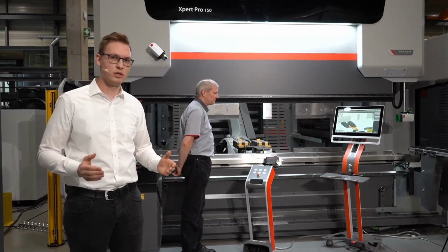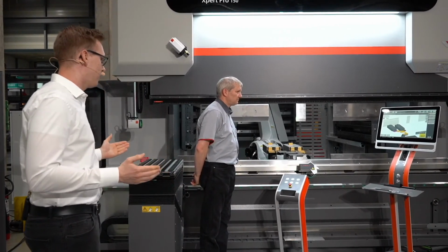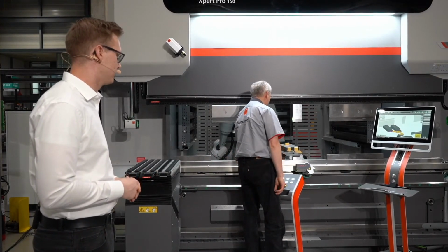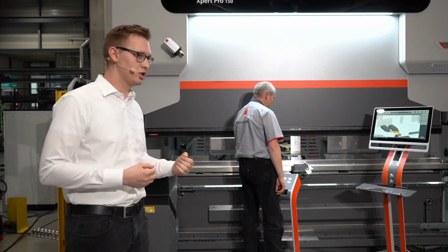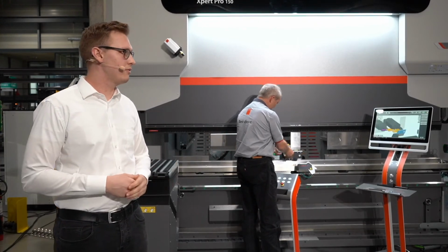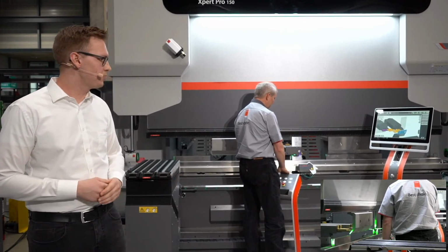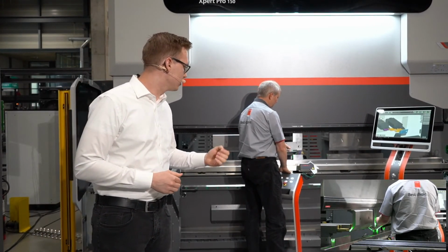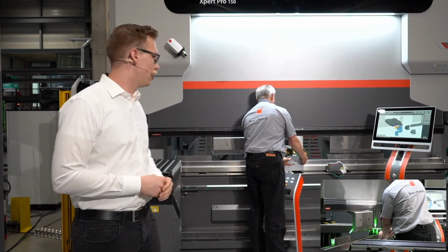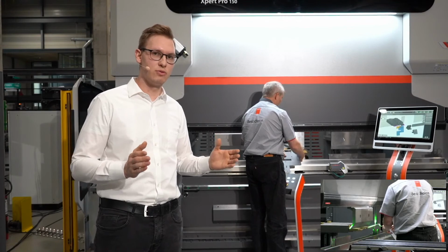With this system, we guarantee that you have a good bend with the first bend. And it is also really fast. You have no more time losses in bending the parts with our laser angle measuring system, because we changed the color of the laser from red to blue, and with this we are no longer influenced by the circumstances in the environment. So we are more process safe, and also the cycle times of the measurement are faster than before. Also, you can now measure really thick parts up to a V of 200.